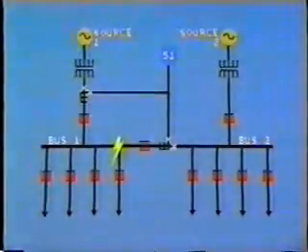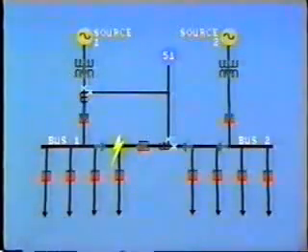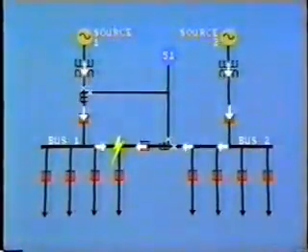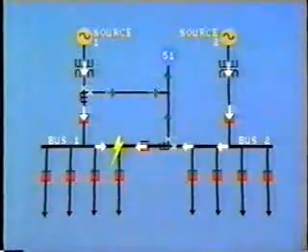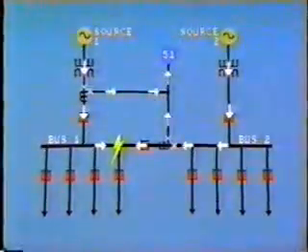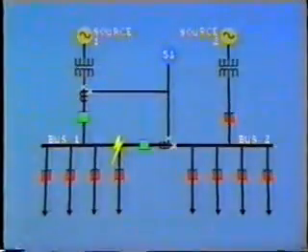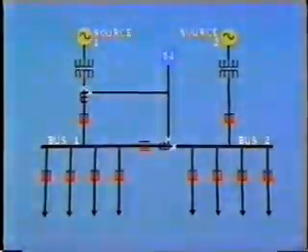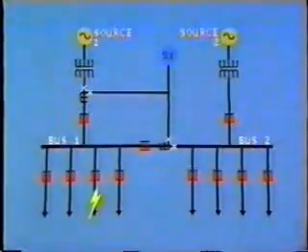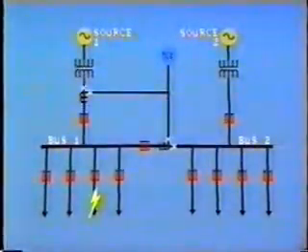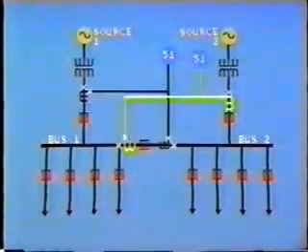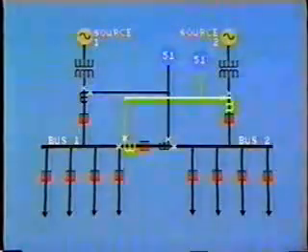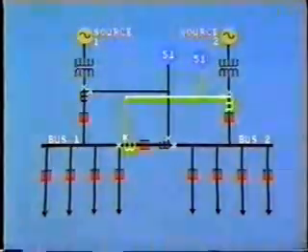Now, if a fault occurs on bus 1, then heavy fault current will flow into bus 1 from source 1 and also through the tiebreaker from source 2. The current in the 2 CTs will now be additive and consequently will cause the overcurrent relay to operate. This protection will also operate for a heavy fault on a bus 1 feeder, which fails to be cleared by its own breaker. The system therefore operates as backup, and the setting of the relay must allow for this. Of course, a similar pair of CTs will be connected to provide partial differential protection for bus 2.